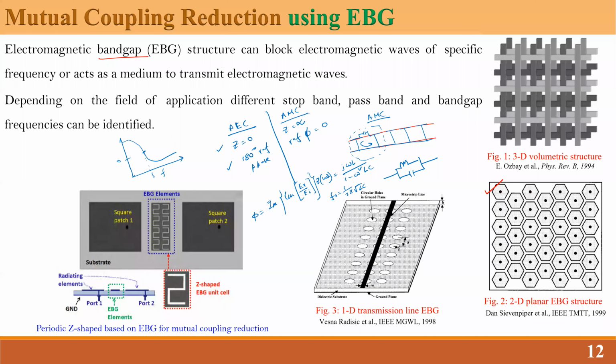That is the reason why: at high impedance, when your impedance will be infinite, when you encounter the resonance frequency, you can see these simplest expressions. When it gets the resonance frequency, then only you will get the perfect reflection, I mean high impedance or infinite impedance, ideally. And what will happen at infinite impedance? Your reflection phase will be 0. So this is the way one can easily think about it.